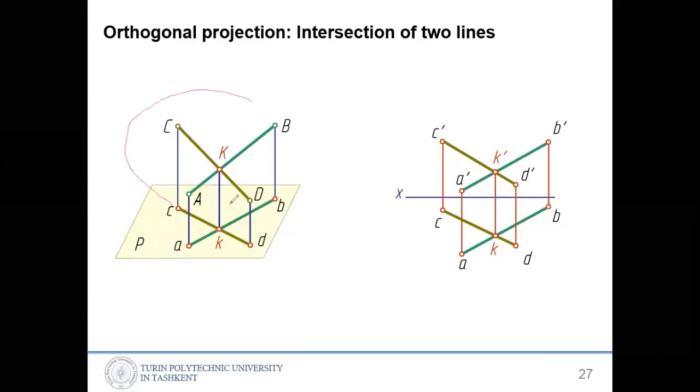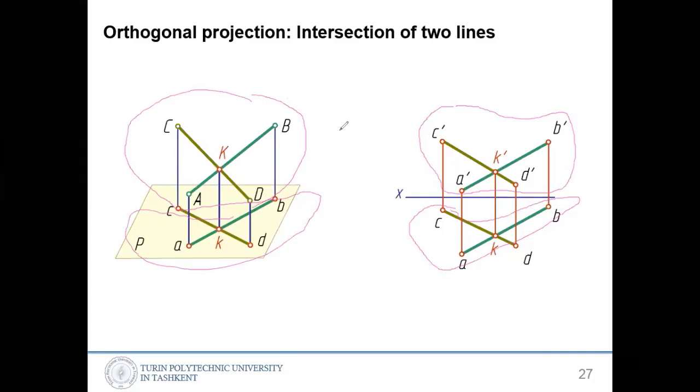These 2 intersected lines are given. That's a projection. That's a projection. So the rule is, again, if the lines are intersected with each other in the 3D space, then in their projections also they will intersect. If any of the projections are not intersected, that means in the 3D space those lines are not intersected. Okay, understood? Okay, I will repeat it.